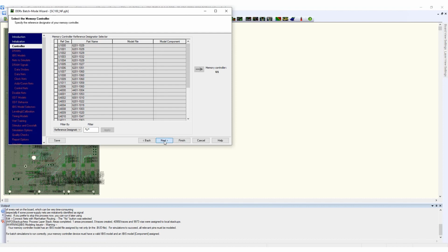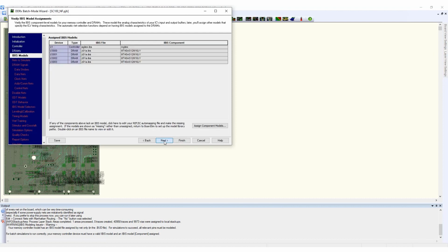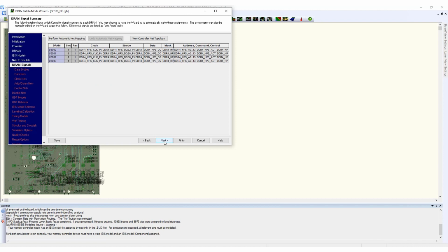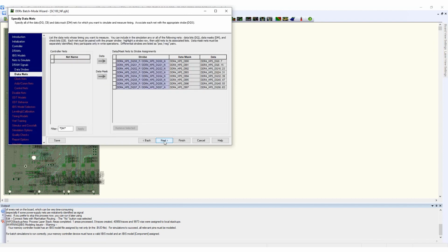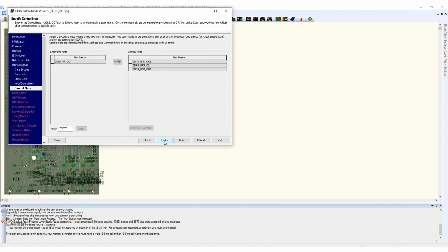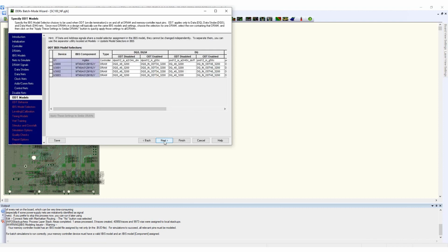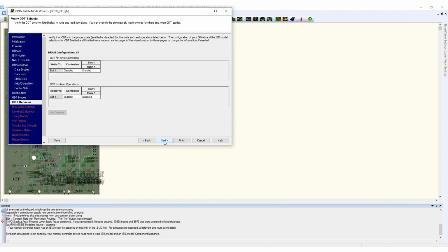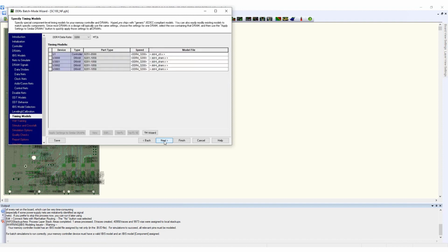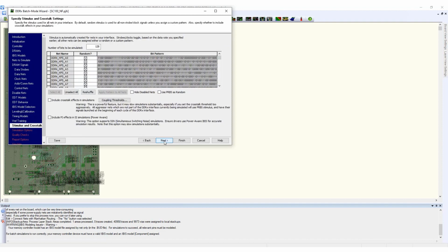The DDRx wizard helps us to configure a complete DDR4 test bench. All requirements from timing margin to signal integrity characteristics are considered. With the different ODT settings, HyperLynx is capable of simulating the read and write use case. Since this is just a fast first check and time to results matters a lot, we will uncheck the crosstalk and power-aware simulation. These checks are done in the final sign-off by Rory.